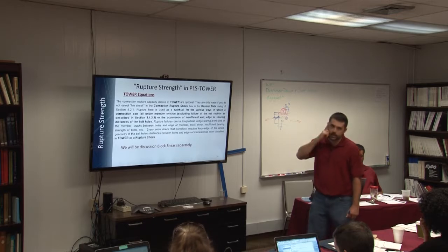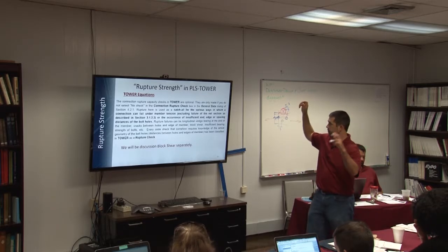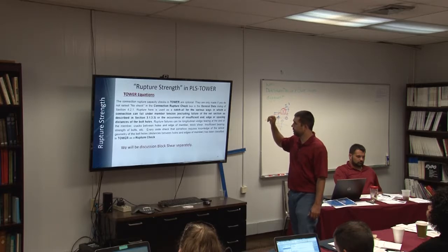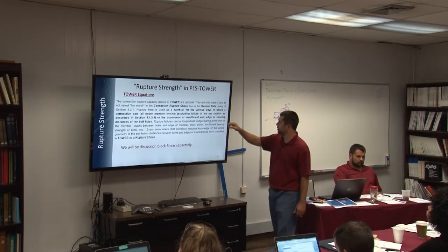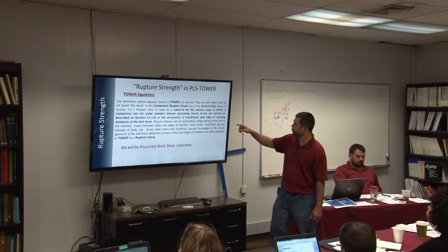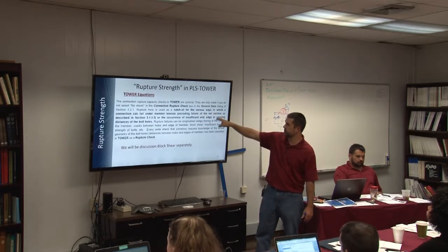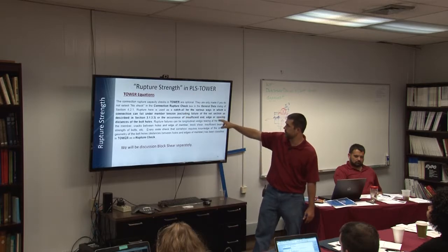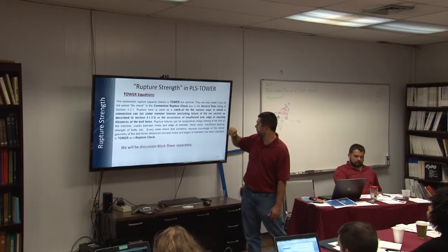So this is what PLS Tower has to say about rupture. The rupture checks are optional. Rupture is a catch-all for various ways in which a connection can fail under member tension, excluding net section, or the occurrence of...